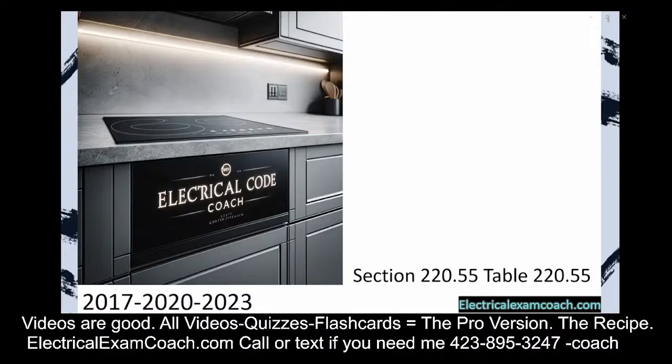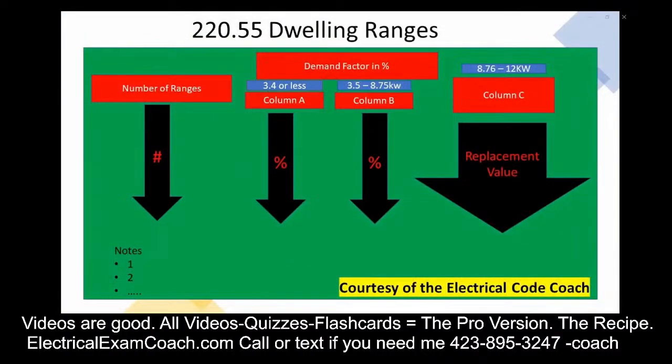Let's get to it. When we get to table 220.55, we're going to read the black bold heading at the top of the table to make sure that we're in the right table. Then, starting on the left-hand side, we're going to find our number of ranges: 1, 2, 3, 4, 5, and so on and so forth. Then we're going to notice that there's 3 different columns. They're really in 2 different groups. Column A and column B are grouped together under the demand factor in percentage column. The reason that's so important for us to watch out is because column A and column B are multipliers. They're actual demand factors. But column C is a replacement value, and you'll understand more of what that means as we get farther through this video.